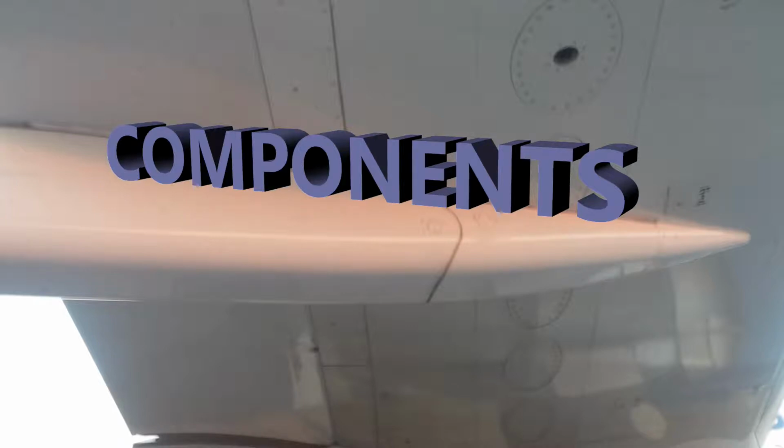It's going to be computing the fuel mass that's held in each of the wing tanks and also the center tank. Remember I mentioned the fuel mass and density. The probes have to do with the fuel density, which leads to being able to calculate the fuel mass. So this computer is computing the actual total fuel mass and also the pre-selected fuel mass.